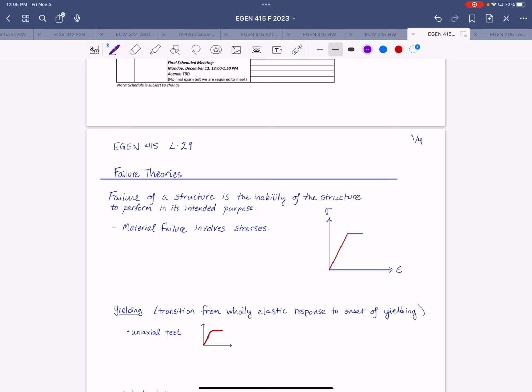Another way to do it, and this is the approach that the solution takes: from the very beginning, you could include the dummy load on the beam and do all of your statics, writing all of your reactions in terms of Q, Fi, and then whichever support you choose to release, maybe RB. And then you're still going to solve the integral with respect to the partial derivative of RB. So that just means a lot of things are going to simplify. You won't have the dummy load showing up, but you'll have the equations already set up in terms of the dummy load, so you could do it that way as well.